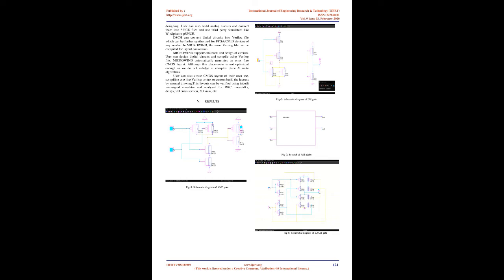Let us consider an example of n-bit multiplication: n² AND gates are required to generate the partial product terms, and the number of reduction stages is given by S = log₂ n. Basic building blocks of the multiplier: formation of partial products using AND gate logic; reducing the n partial products to 2-row partial products by compressing the columns with (3,2) and (2,2) adders; merging the 2-rowed partial products with carry propagation adders.